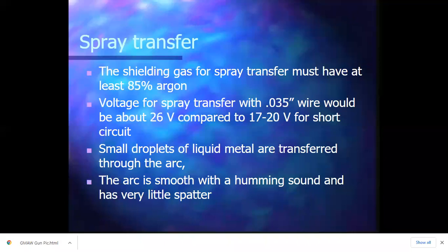What you're going to notice is when you're welding short circuit, your MIG gun's going to have feedback because that short circuit steel comes down, touches the puddle, and then it pinches off. So you have physical contact with that puddle time and time and time again. So when you get to spray and globular, it feels different because that gun is no longer making contact with the puddle. It's shooting bits across the arc. So it's going to feel different, feel a little more smooth. Spray set up really nicely is just beautiful.